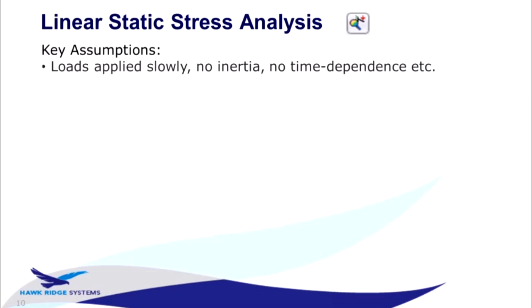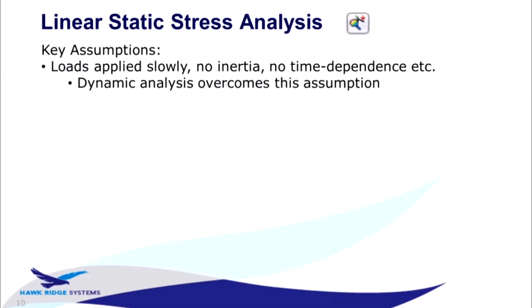First one is that we assume that any loads that are being applied are applied gradually or slowly. If I'm applying a load to the table that's in front of me right now that you can't see, I'm pushing gently on that table until the full load is applied rather than striking it with my hand or something like that. So we assume that loading is static, basically. And if that assumption is no good to us, we need to move on to a dynamic analysis type instead if we want to analyze a shock or an impact or a vibration or anything like that.